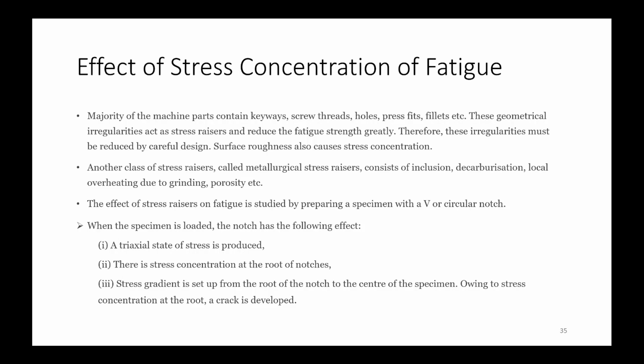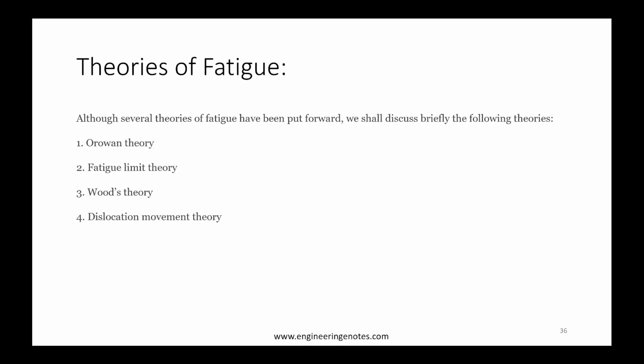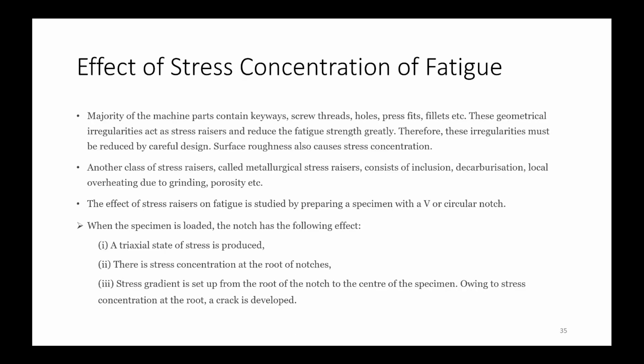Owing to the stress concentration at the root, a crack is developed. These are the reasons that your surface should be finished very properly. It should be polished smooth to improve the fatigue life of your material or your machine component.